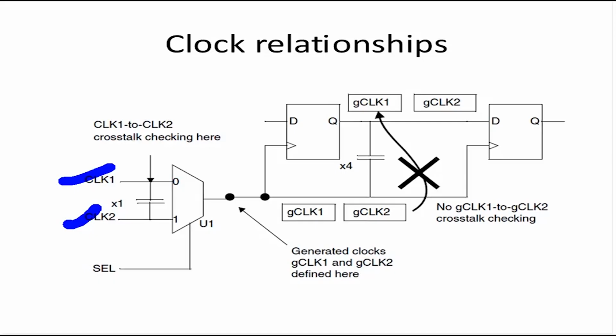So we talked about noise and crosstalk. Both are caused by the same physical effect. Noise is the case where the victim is static. Crosstalk is the case where the victim is switching, and the crosstalk causes the victim net to have a worse or a better transition and a worse or a better delay. Since this is the delay part, this will affect our setup and hold timing in exactly similar manner as OCV.